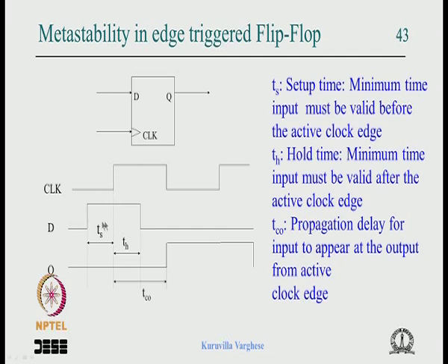So the setup time would normally mean, from the active clock edge, that is from when the master is going to be cut off from the input, the minimum time required for that latch to set, because that is the latest the input can change. If afterwards the input changes, there is not enough time to set the master latch. So that is the setup time.